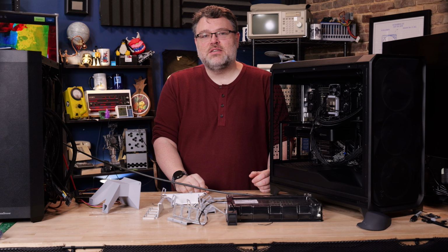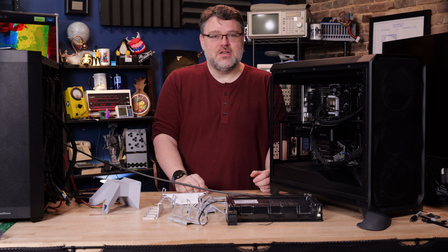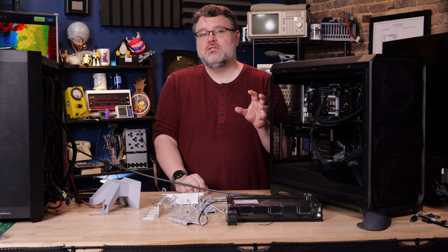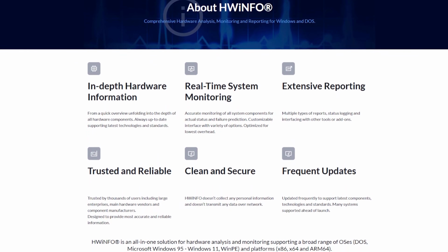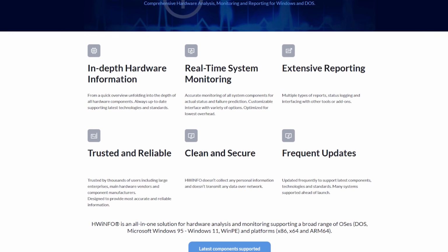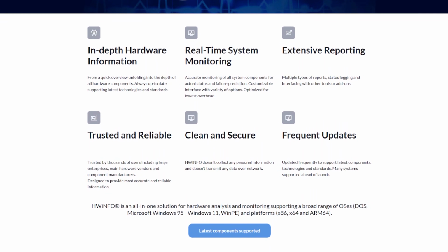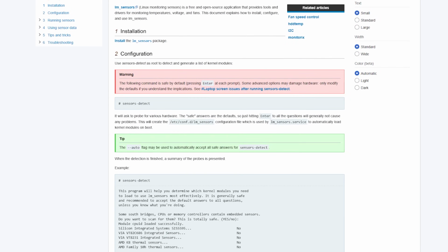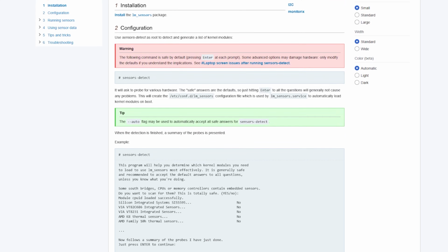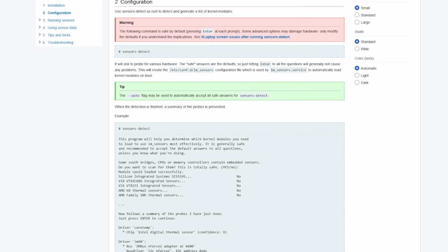If you're running DDR5 desktop or workstation, do this. Monitor your DIMM temperatures. How? On Windows, there's HWiNFO64. This is an excellent program that has never let me down. We use it in a lot of our videos. On Linux, lm-sensors and RASDaemon. RASDaemon is a killer app. It should be installed and enabled by default. A lot of our Linux how-tos have that.